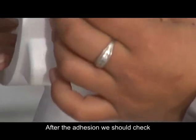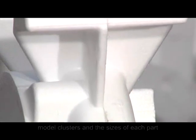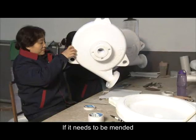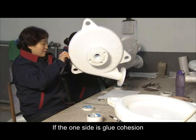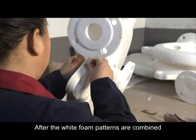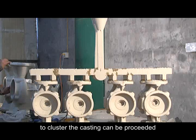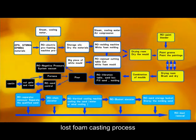After the adhesion, we should check the adhesion joint, the surface of the model clusters, and the sizes of each part. If it needs to be mended, we can mend it with masking paper. If one side is glued, the other side can be coated well. After the white foam patterns are combined into a cluster, the casting can proceed, which is the so-called black area of the lost foam casting process.